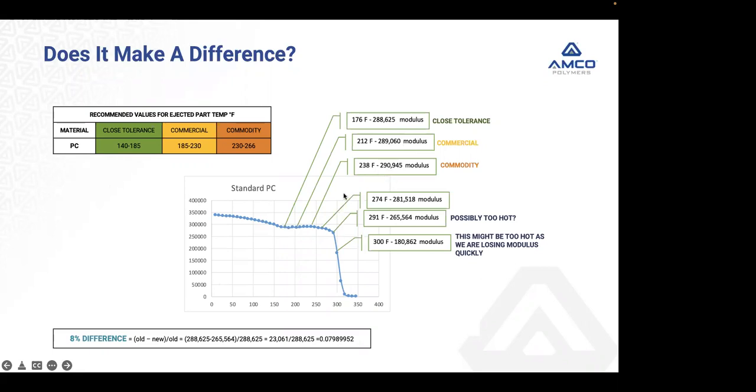And here my modulus is slightly higher again. So they're saying, wait a minute, as I get out here, you're saying you get a tighter tolerance out here? And that kind of confused me because I'm like, wait a minute, my modulus doesn't change. Warp, pin push, all has to do with the modulus of the steel. Obviously, your draft and ejector pin size make a difference, but does 1000 PSI really make a difference?